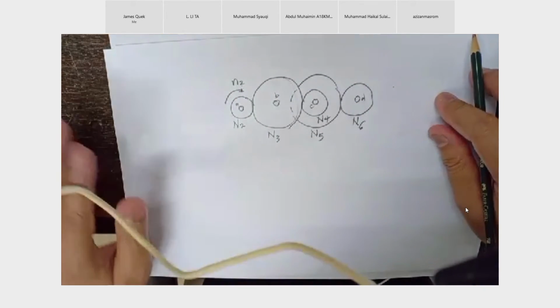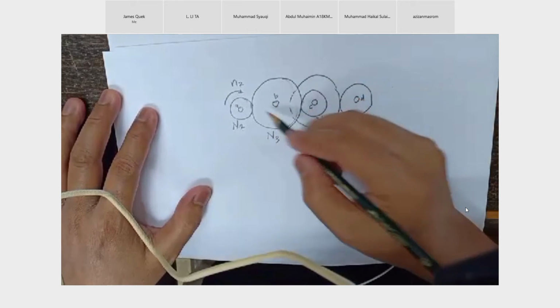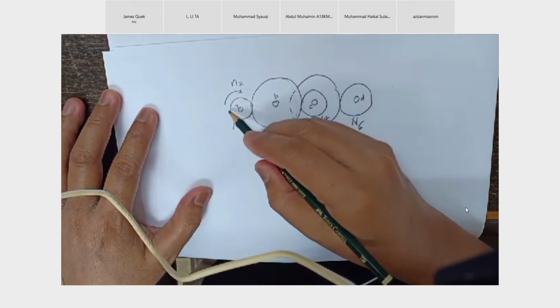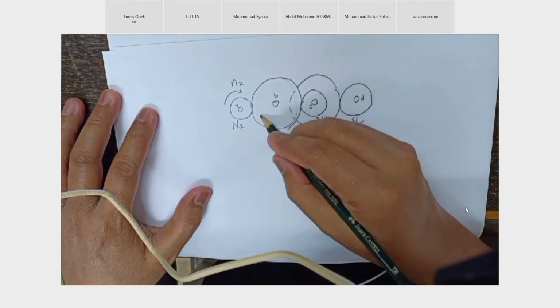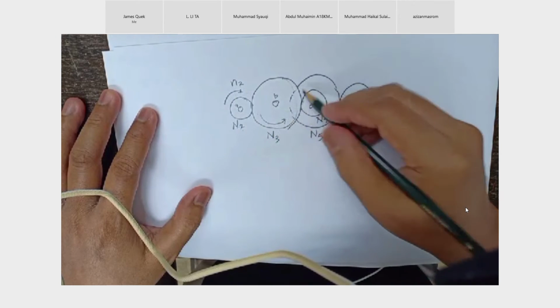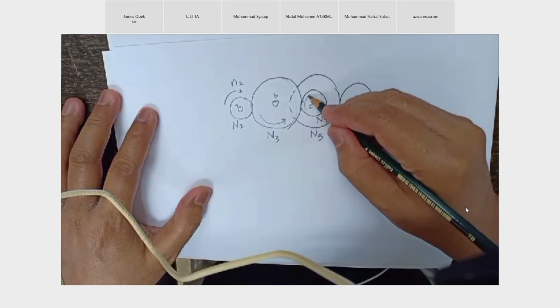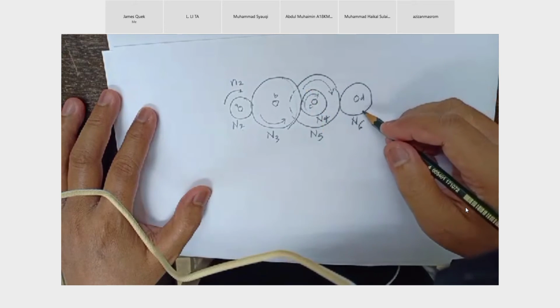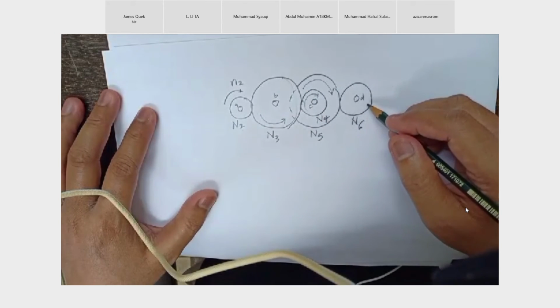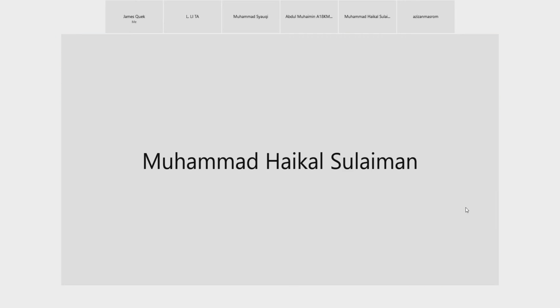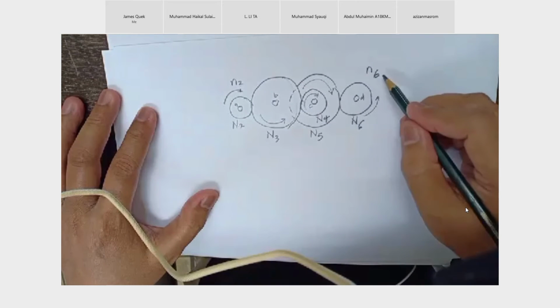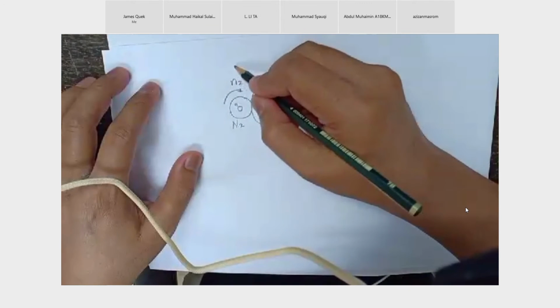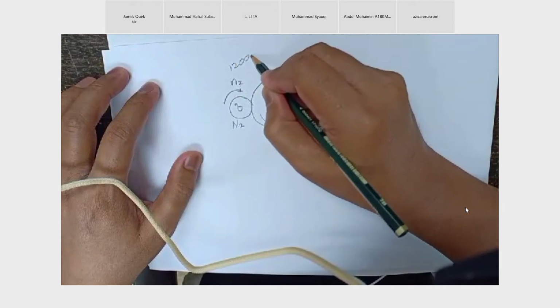So this one would drive. The mating gear always reverses direction. If this one is clockwise, this one will be counterclockwise. Gear 4 will be clockwise again. Gear 5 also maintains clockwise, right? Can you see my writing? And this one will become counterclockwise again. But the question is, the first thing you should know, what is your N6, the output speed, RPM, angular velocity here? Given here, say this one is 1200 RPM.